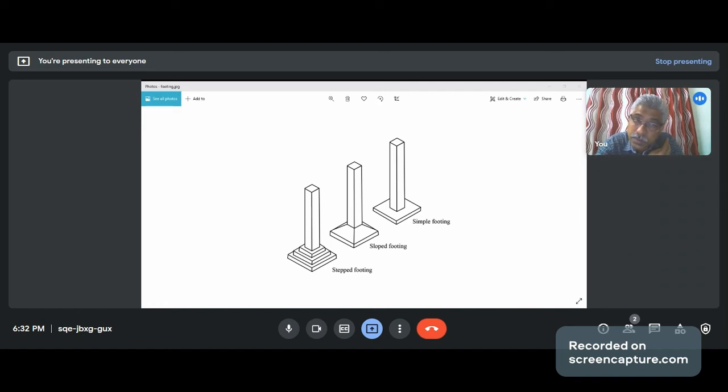So there are two types of shear failures possible in the slab. That is, the column as a whole may pierce into the slab, or the slab may shear, if you can see that if this is the slab, this slab may shear like this as two pieces, or otherwise a column may pierce into this. When a column is piercing, we call it a two-way shear.